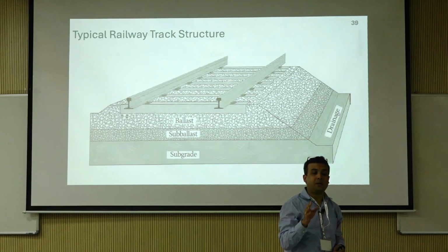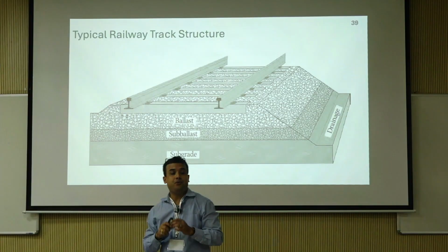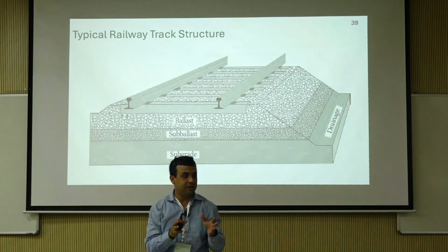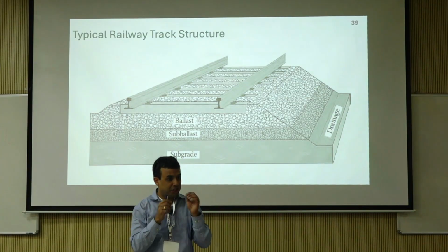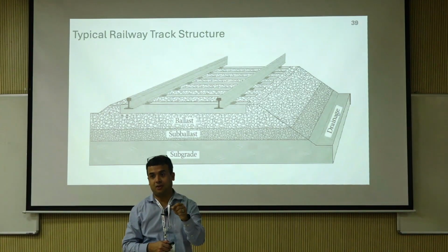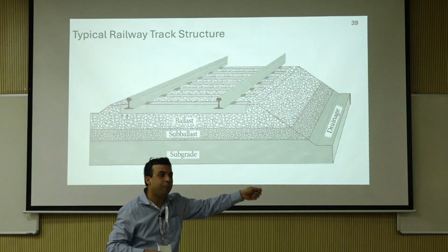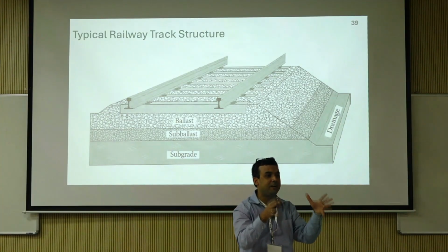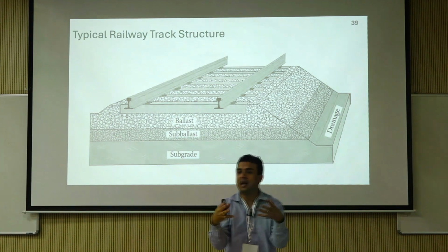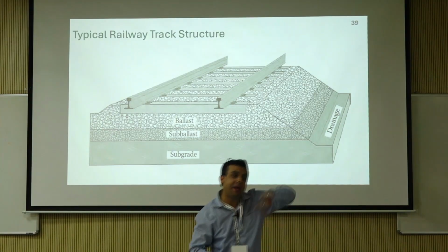But one thing you really need to understand is, if you have a fouled ballast in the middle of a desert, where it's dry, the shear strength of that ballast, or sometimes the modulus, may actually be better than an open graded ballast, because now the fines are stabilizing the matrix a little bit and the system is actually more like a well graded system than an open graded system. The problem happens when it rains.